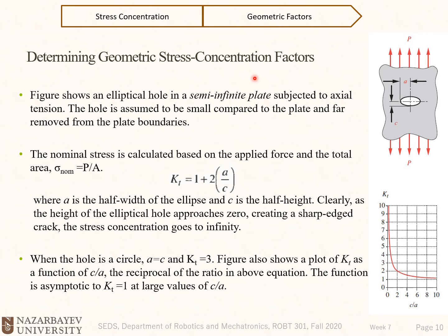Determining geometric stress concentration factors. The figure shows an elliptical hole in a semi-infinite plate subjected to axial tension. So here we have our elliptical hole in this plate. The hole is assumed to be small compared to the plate and far removed from the plate boundaries. So these boundaries are far from the hole.